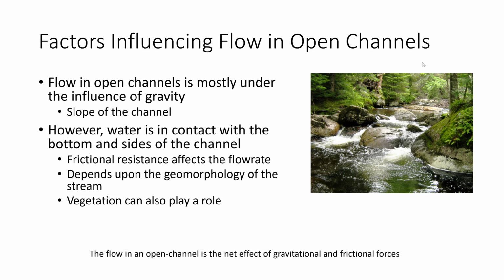Frictional resistance also depends upon the geomorphology of the stream, whether we have very large rocks or fine particles at the bottom of the stream or channel. In addition, vegetation also often plays a very important role in controlling the flow of the open channel.